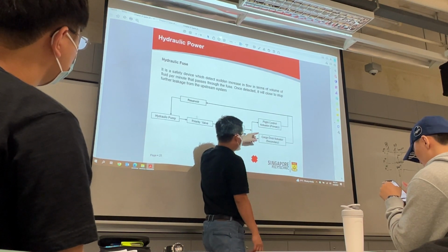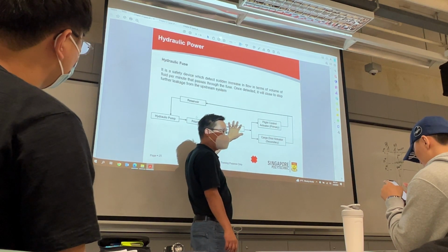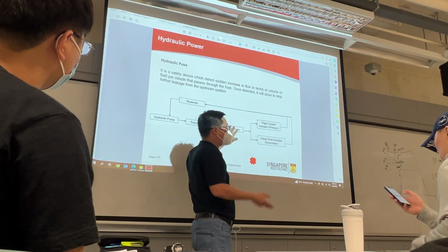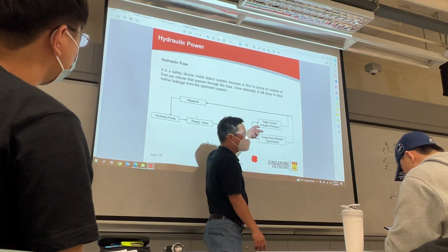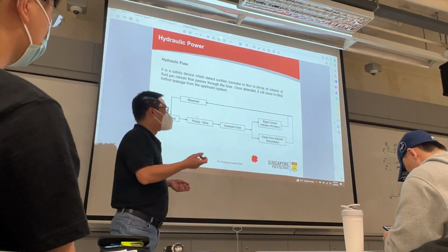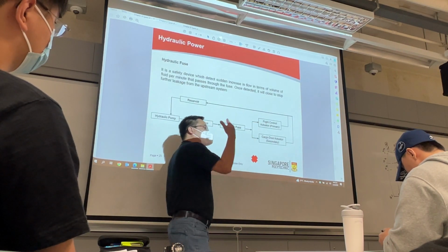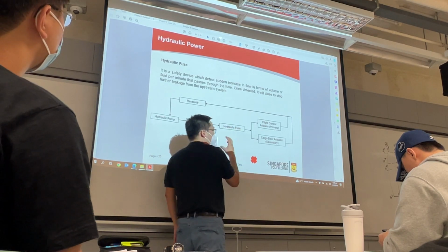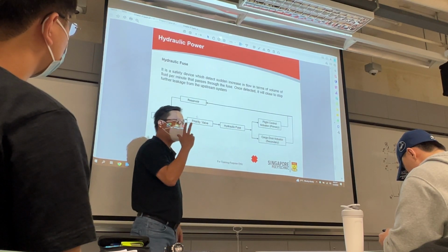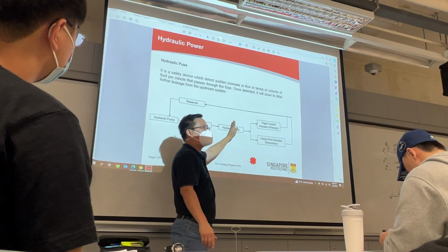If there's a piping here, usually hydraulic fuse will be employed somewhere at the engine bay area, where there are hot surfaces. So if let's say there's a pipe here, the pipe broke. Ask the class, what happened to the flow rate? Increase, right? When it increased, the fuse inside, there are some springs. They know that the flow has increased to a certain limit, right? It will stop the fluid from leaking anymore.